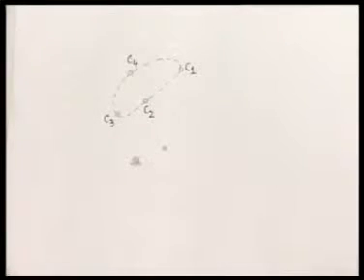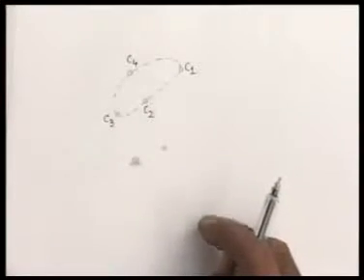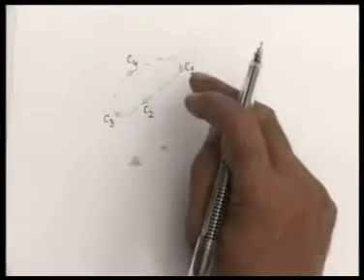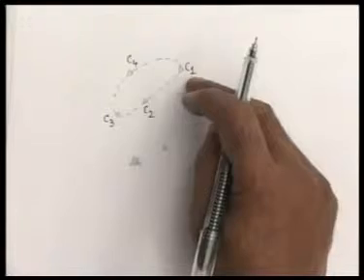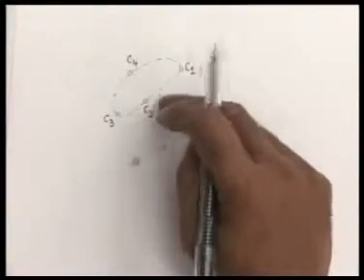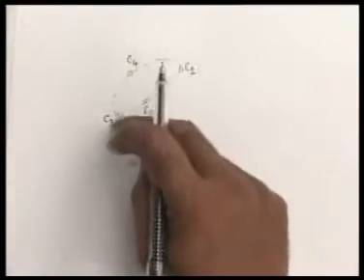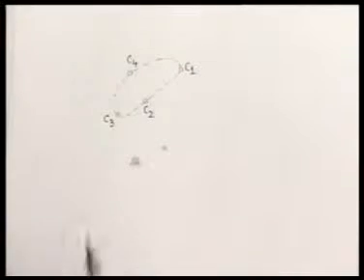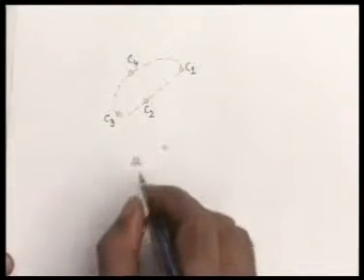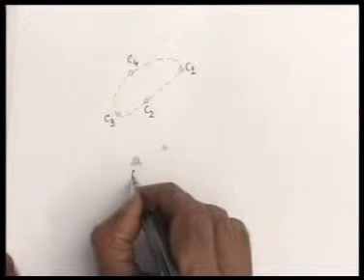We will design a 4-bar mechanism to generate this coupler curve, only ensuring that the coupler point C passes through these 4 positions C1, C2, C3 and C4. As explained in the last lecture, what we do, we choose O2